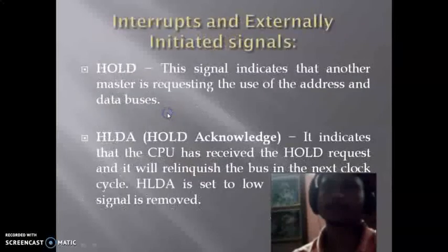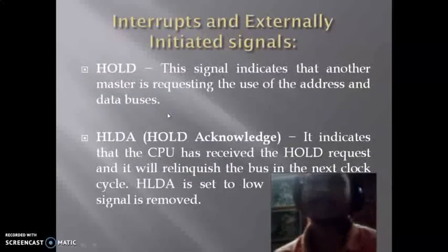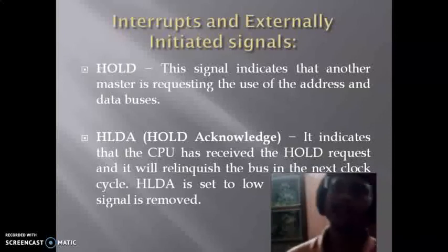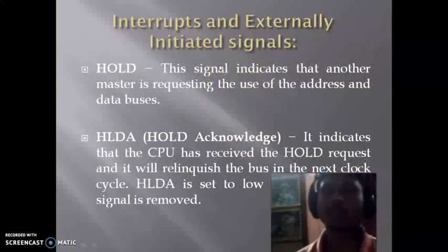Next, HOLD and HLDA signals. These are also externally initiated signals. The hold signal is basically used for DMA operations. If some peripheral device wants to access the address or data bus of the 8085 microprocessor, then it will send a hold signal to the microprocessor, telling it that the peripheral device wants to use the address and data bus.